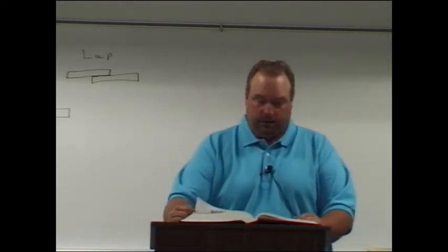Let's talk about some of the welding on low carbon steel plate. It's common practice to limit the application of oxyacetylene welding to low carbon steel plate with a maximum thickness of about 11 gauge or 1/8 inch. Usually 18, 16 gauge, 14 gauge, down to about 11 gauge. That's about what's usually done with low carbon steel.